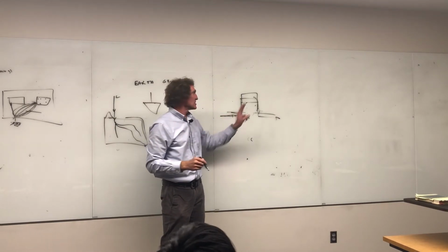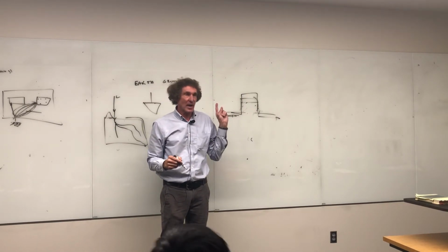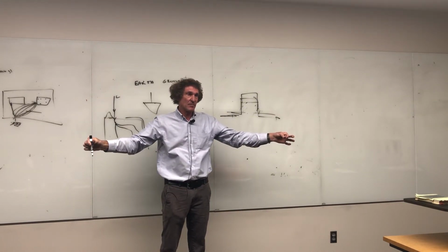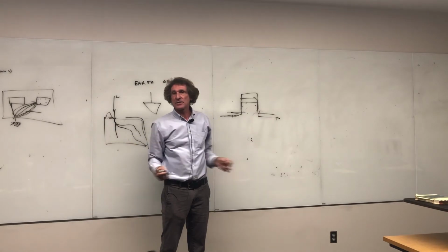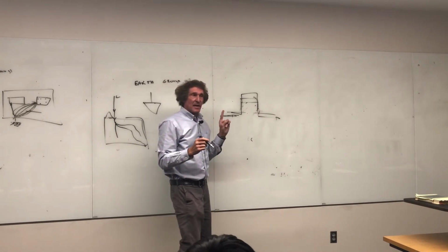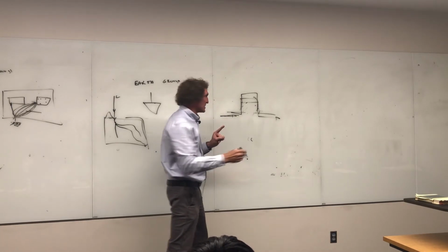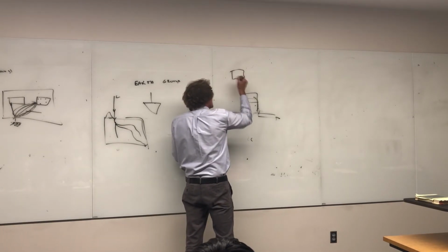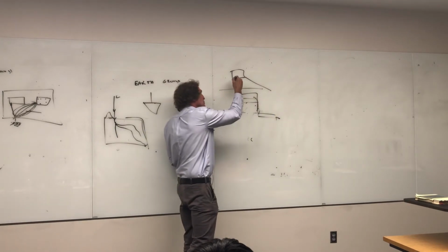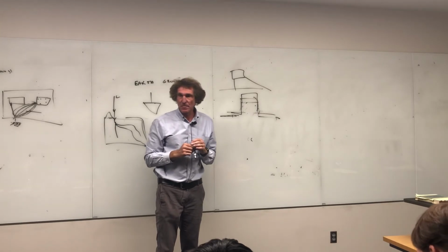When you make ground connections with anything, only one ground connection, unless it's lightning protection, where you can take 2 to the ground, on opposite ends. But when it has to do with anything else, it can be grounded at only 1 point, and try to make it the shortest possible ground connection. In other words, if you have a product like this, and this is your ground, don't have it like this. All right. Have it straight down, the shortest possible distance that's feasible.